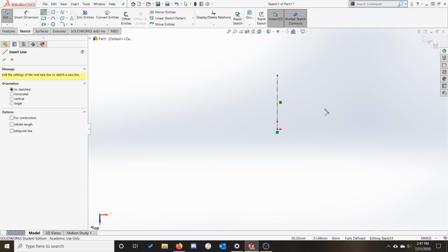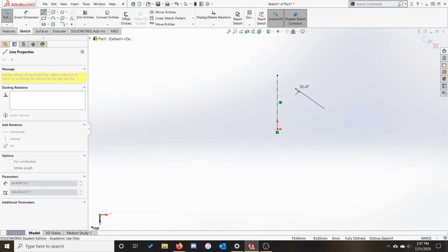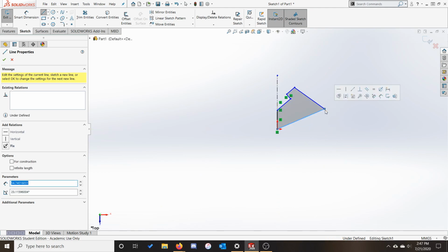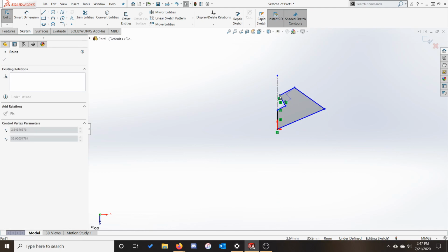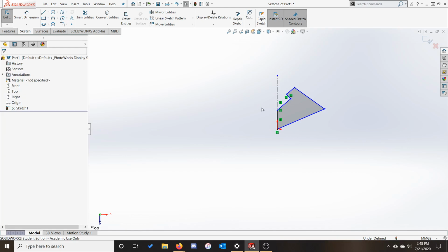First, the revolve profile cannot cross the axis of revolution. It has to be drawn completely on one side of our center line. Next up, the revolve profile cannot touch the axis of revolution at any single point. Contact between the axis and the profile must be along continuous edges, like this. A shape along these lines would be acceptable for a revolve profile. But if this endpoint here were to be in contact with our axis of revolution, we would have an invalid revolve sketch. Breaking either of those rules is going to have SolidWorks give you an error message.